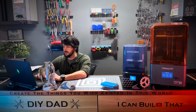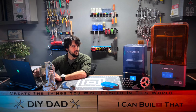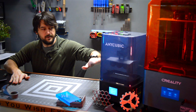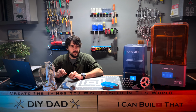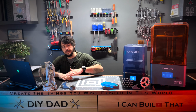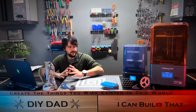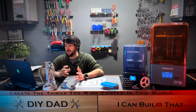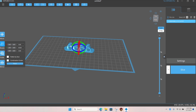The reason I show you this is that it's important to know that with a resin printer compared to an FDM printer, the length of print is determined by the height of your object. A resin printer can cure an entire bed, an entire build plate surface layer all at once. So it doesn't matter how full your build plate is, it matters how many layers it has to cure in the vertical orientation. So the higher your object goes, the longer it will take to print. So with that, we can adjust our prints so that they lay relatively flat on our print bed and reduce the printing time needed to print those objects.